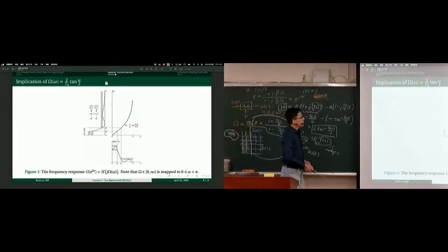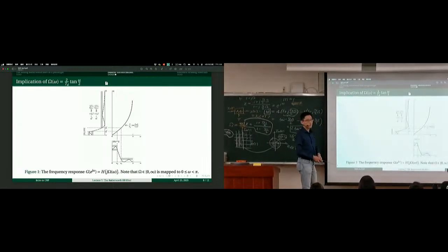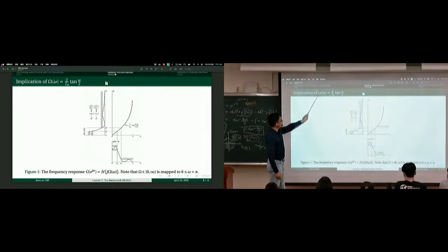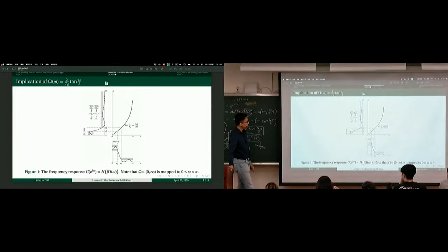But now coming back to focus on this equation, big omega as a function of small omega. This relation explains the relation between the analog prototype and its discrete time design. Long story short, it's about compressing the frequency axis.